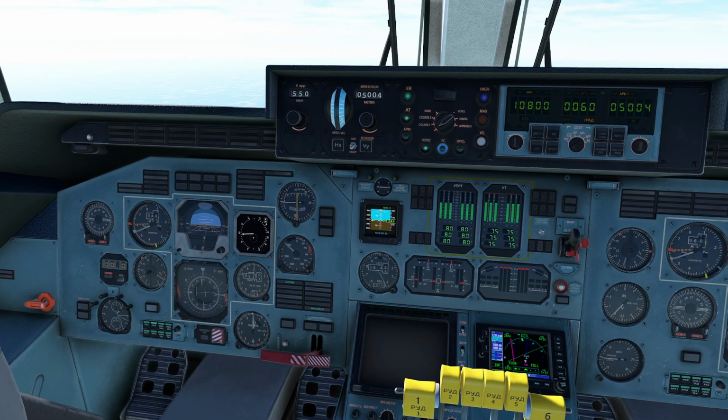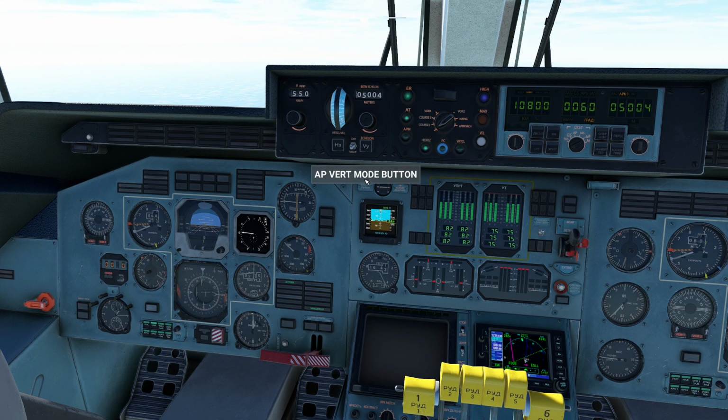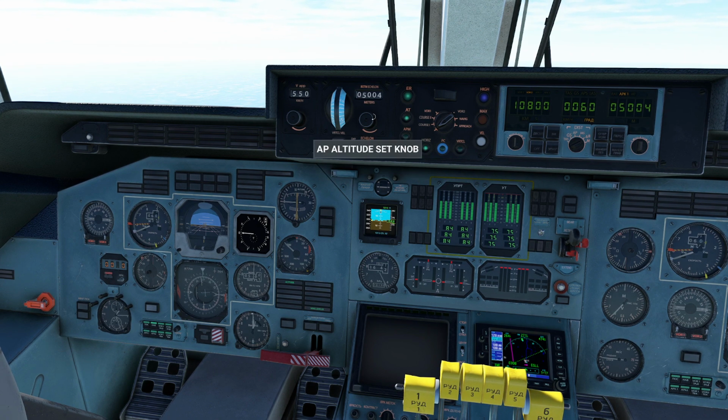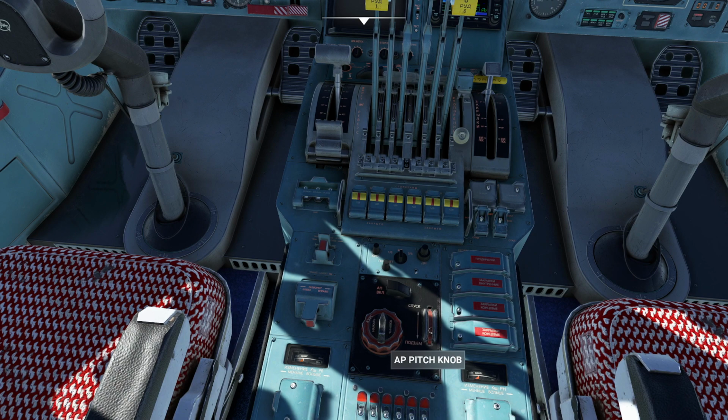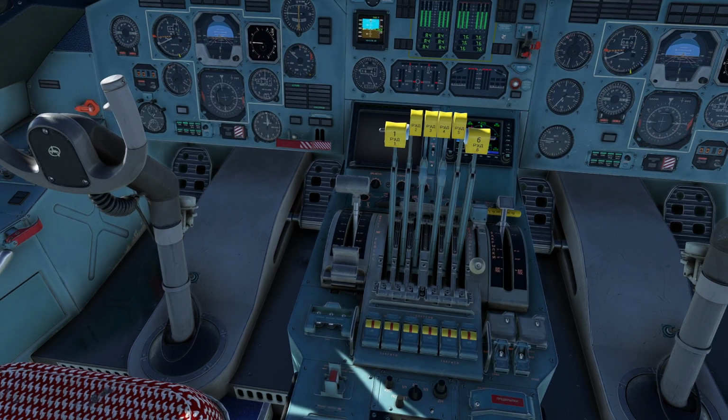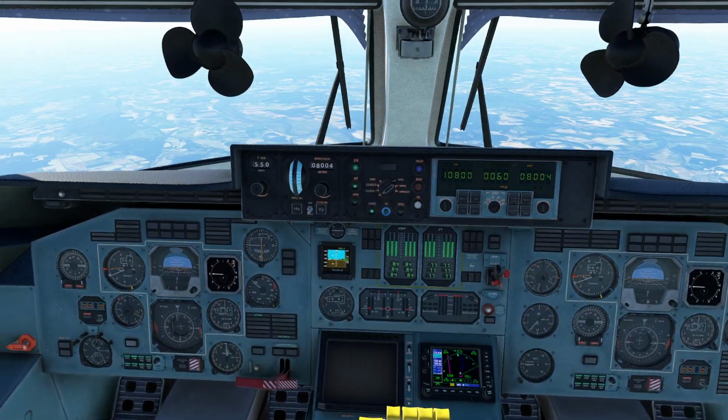That's just kind of the nature of that beast. Watch out, though, because it will lock on to whatever altitude that you desire it to do. So that's not necessarily something that you want. You have to make sure that you pick a really funky number here to get that nose going up. So if I were to pick, let's say, 7,000 meters over here, and then I would come over here and start manually cranking on this thing, this will give me the pitch that I need to be able to start climbing up to that altitude.